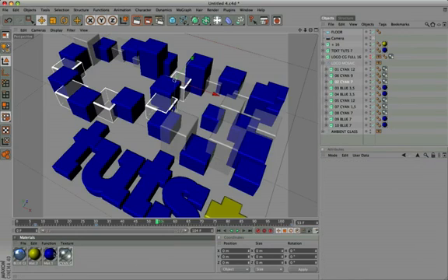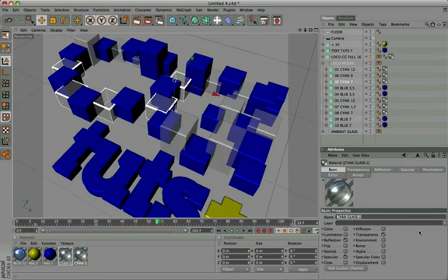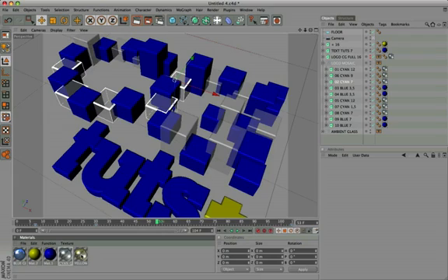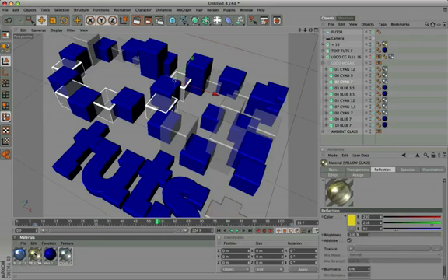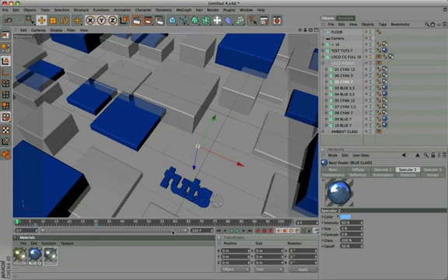Duplicate the material just created, and rename it yellow glass. Change the color only in the reflection panel to 230, 216, and 56, and the brightness from 90 to 100. Replace the yellow material just created onto the existing one, dragging it over it while pressing the Alt key. Also replace the blue glass material. With this simple step, we included all the materials in our scene.